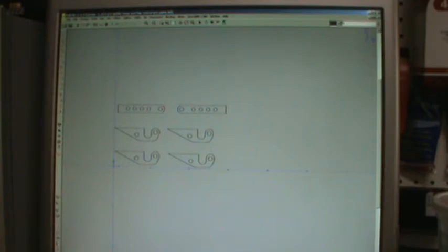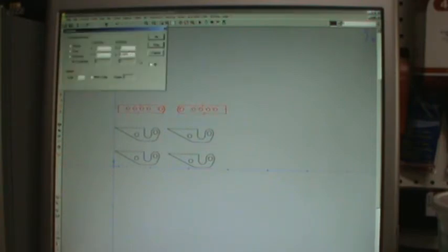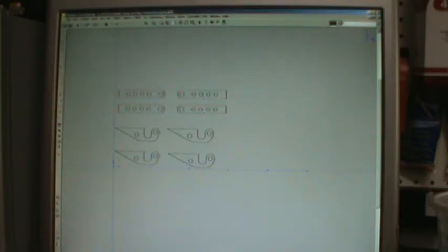Now we got those parts in. Let's do 2 extra ones of those just because we can. Do make a copy, not 3D. And same thing, I want to translate that. We'll say 3/8 of an inch. And there's our next one.